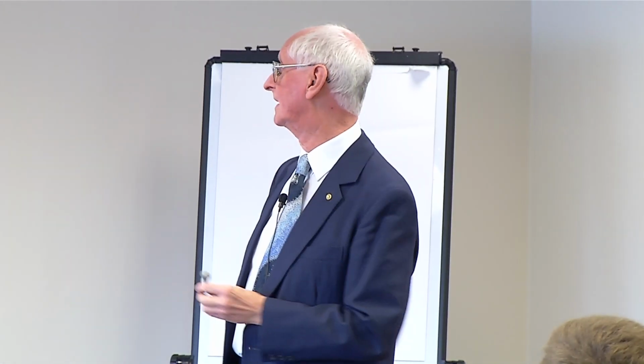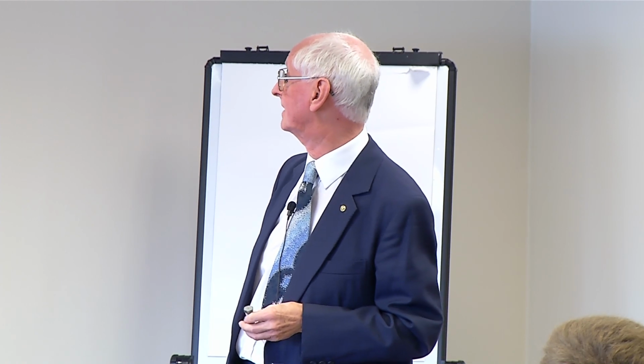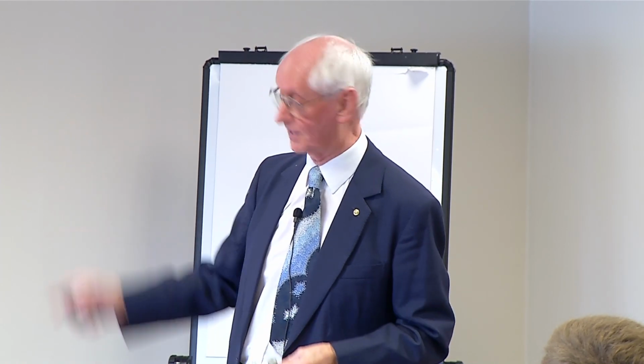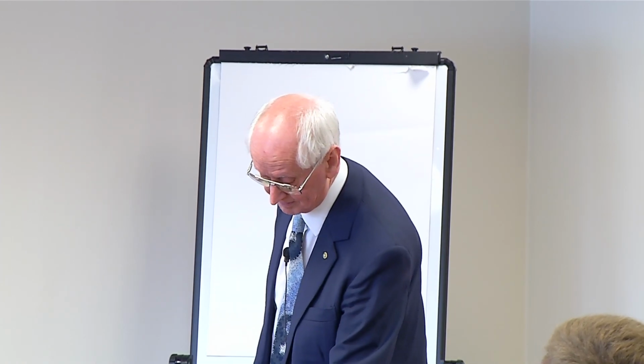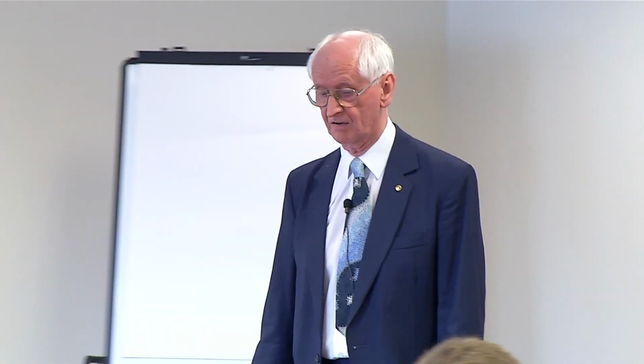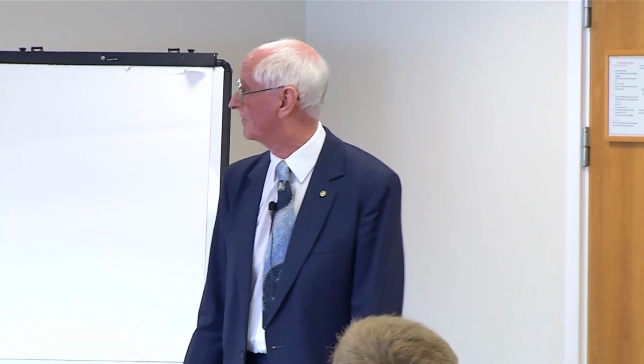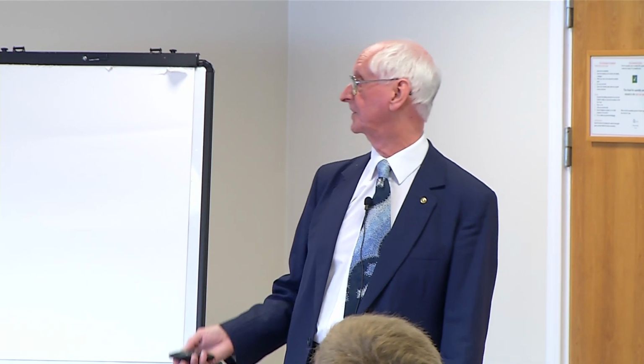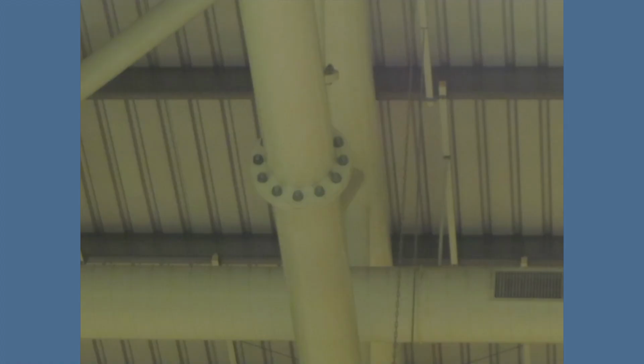They would probably need at least high tension 8.8, possibly even a higher grade for those, because they are performing an absolutely crucial function. And if you look at the end of them, you've got a whole series of them. But if they're the wrong ones, that's not very good.